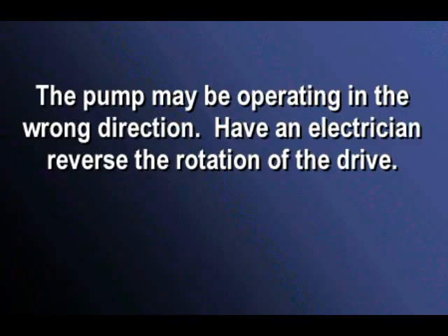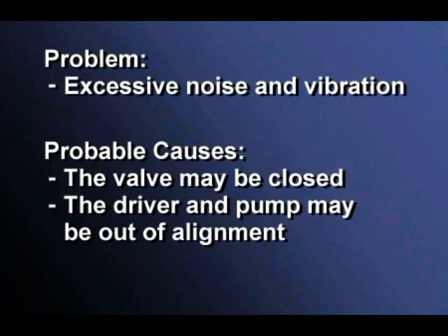The pump may be operating in the wrong direction. Have an electrician reverse the rotation of the drive. If there is an absence of fluid to be pumped, check the fluid level controls. Repair them if necessary. Problem: excessive noise and vibration. Probable cause: the suction or discharge valve may be closed.